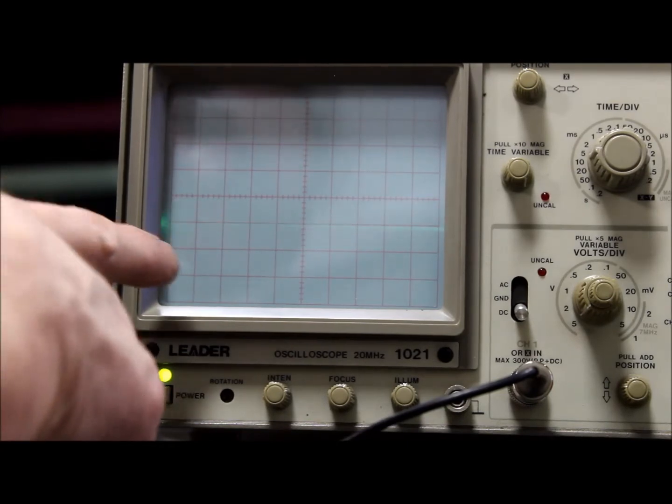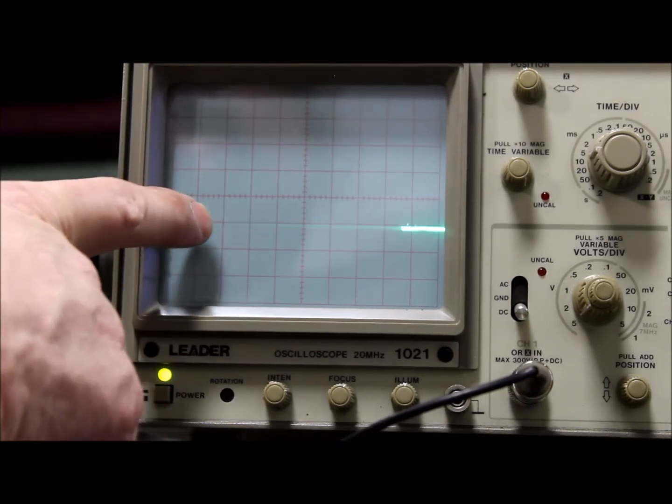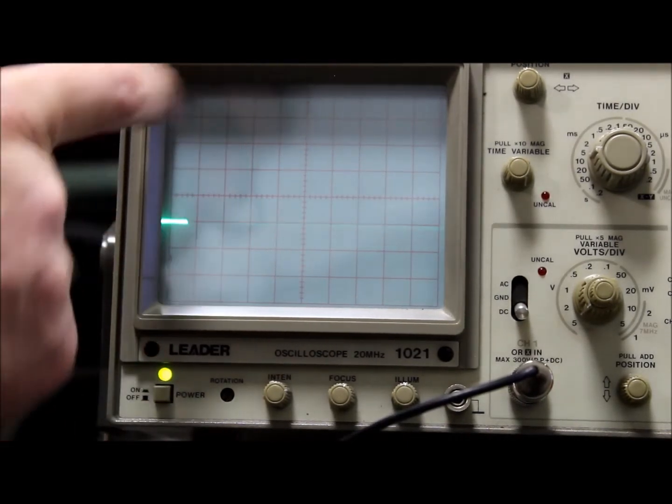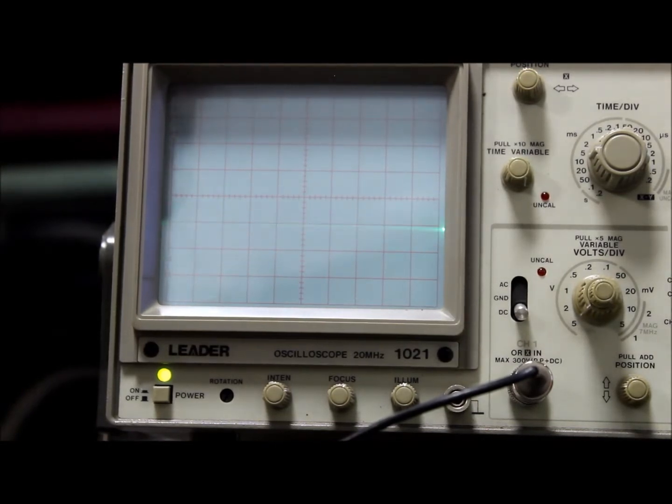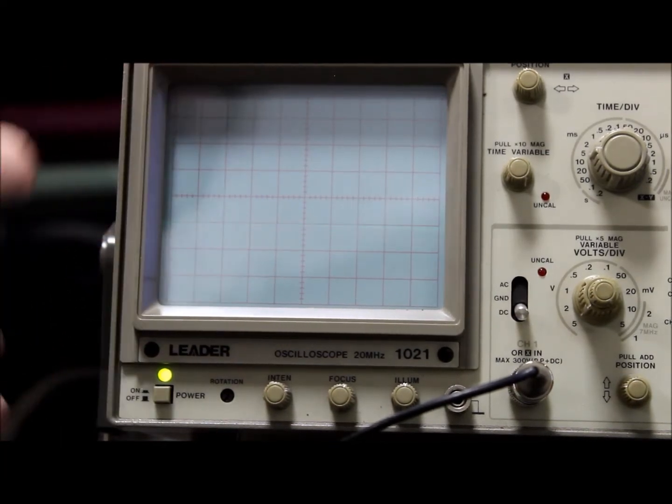Another interesting thing is every time this injector turns off, there's a big spike. Anytime you energize an electromagnetic coil and a magnetic field builds up around it, when you de-energize it, you see that big spike. A lot of devices have something in place like a clamping diode or a resistor that's designed to keep that spike from hitting the computer. It can be several hundred volts. Right now it's going off the top of the screen.